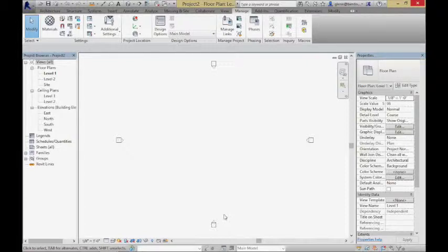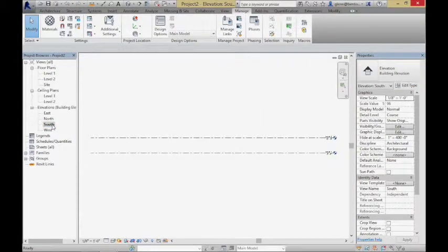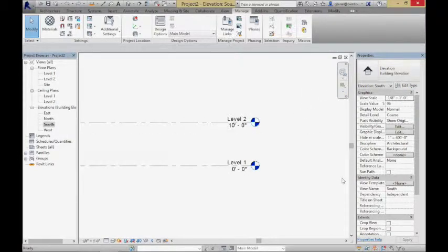The other thing we tend to do is start off with this notion of floor levels. It helps us take a volume and divide it into something that feels like areas. To do that, go to any of the elevations. I'm going to go to the south elevation, for example, and you'll see a couple of floor levels there. Now, 10-foot floor levels is actually pretty small.